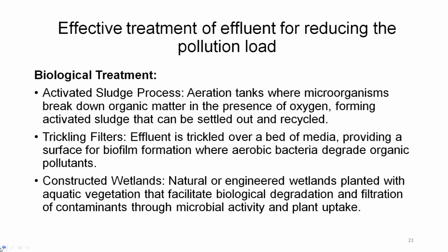Trickling filters, where effluent is trickled over a bed of media, providing a surface for biofilm formation where aerobic bacteria degrade organic pollutants. Constructed wetlands, natural or engineered wetlands planted with aquatic vegetation that facilitate biological degradation and filtration of contaminants through microbial activity and plant uptake.